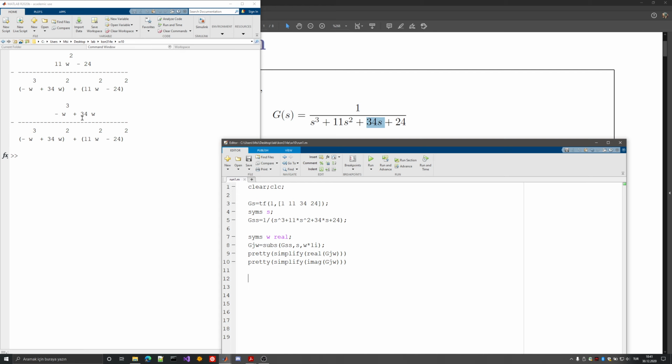So you know the value of omega. This will give you a real part and imaginary part, and this whole thing is a complex number. So the only thing is you have to convert from the Cartesian coordinates into the polar coordinates. Then you will have the gain and phase. Basically, since I know these, I can just go ahead and take the real part and take the imaginary part, and then calculate the square root.